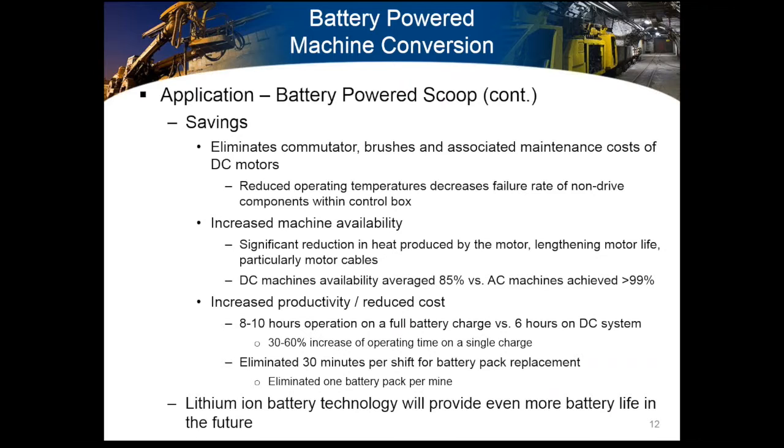In this case also, the mine saw a great reduction in cable connections failures, in failures of those connection points. Over time, as current is passed through those connectors, you'll get stressing and fatigue, particularly in joints. And again, the more current you can reduce, the longer the life of those cables.